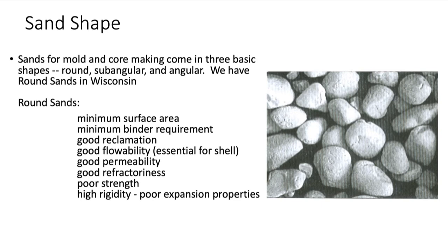That's why when you use gravel, like for a driveway or under concrete, they usually use very angular pieces of gravel, and under railroad beds as well. So round doesn't have as good a strength. If you ever walk down a beach that has large stones that are all round, it's very difficult to walk because you just keep on sinking into them.